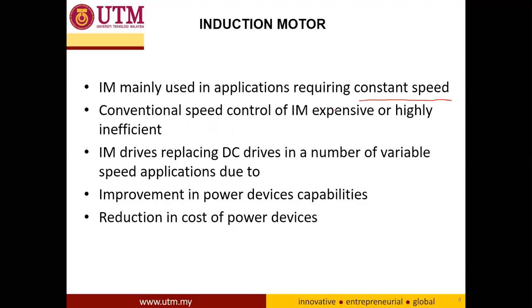And usually, to have a variable speed, they adjusted the voltage supply by using a transformer. Yes, the speed can be varied by adjusting the voltage supply, but in terms of efficiency, it is not as good as when we control the frequency input.